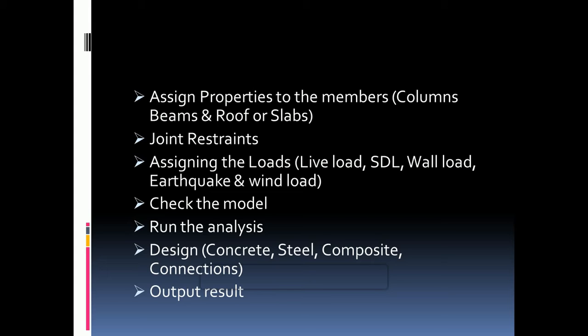Later at the bottom we will fix the base of the model. Later we are going to assign the loads which we have already defined in the previous slides, like the live load. As I told, the live load, dead load, and the SDL. The SDL means the super dead load.